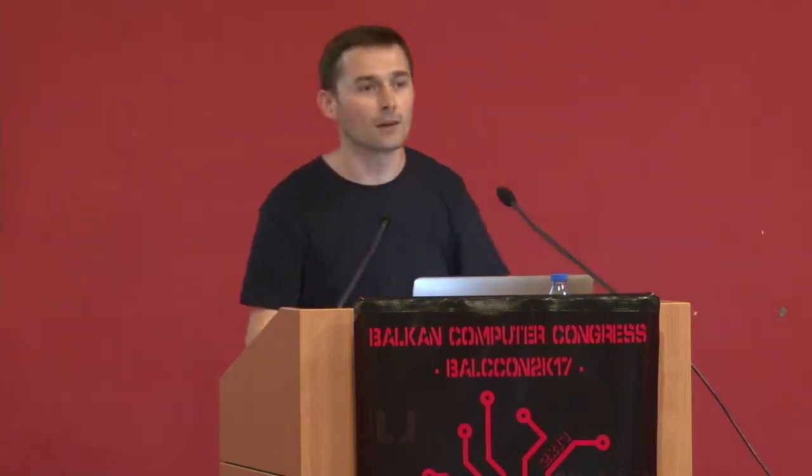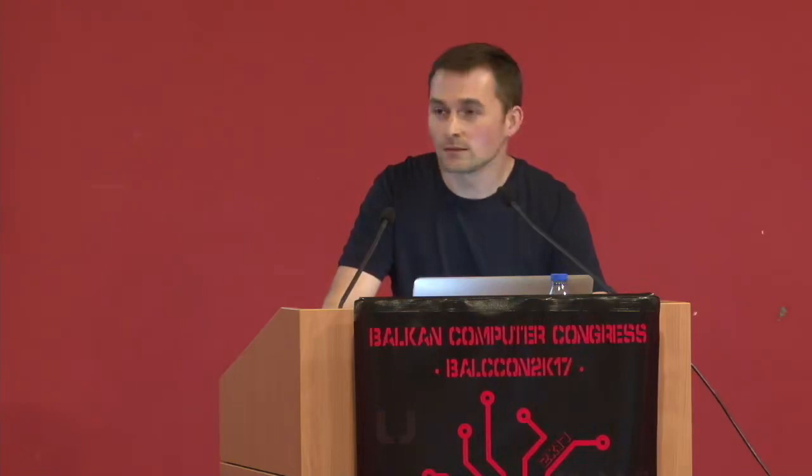What you get of that? Surely you don't want to annoy the people inside. You could use an infrared laser beam, which is invisible, and also, I've learned, safe for the eye, and use a pin photodiode and align yourself exactly 90 degrees in front of the window, enough to get your laser beam back. Anyone knows what comes out of this? The audio. The audio inside the room.